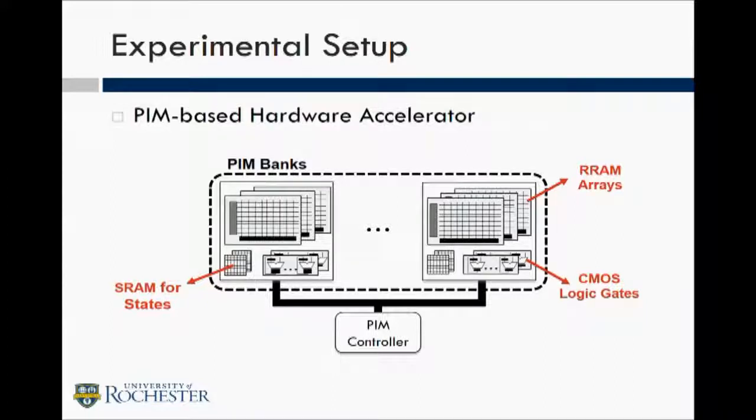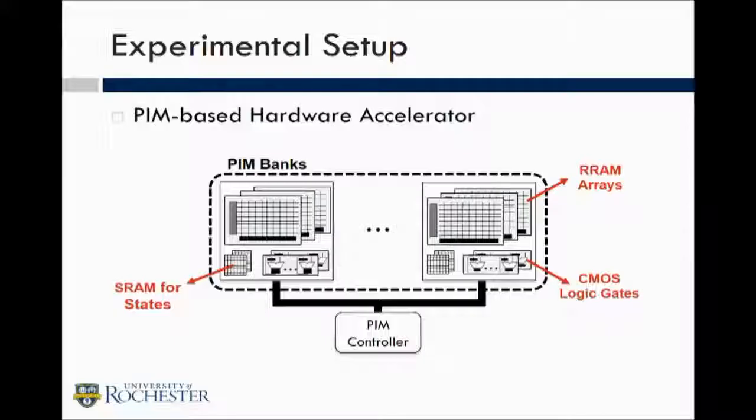So if you told me that you had access to RRAM, I would say, hey, if you want to eliminate data movement, let's just do a PIM using RRAM arrays and conventional CMOS gates. But that's processing in memory. Okay? Just think of it as small amounts of computational units right next to individual memory arrays in a memory chip. Okay, so whatever the benefits of analog computation are, it has to be compared to this, because this is the right baseline. Stuff running on a CPU or GPU is simply not the right baseline.